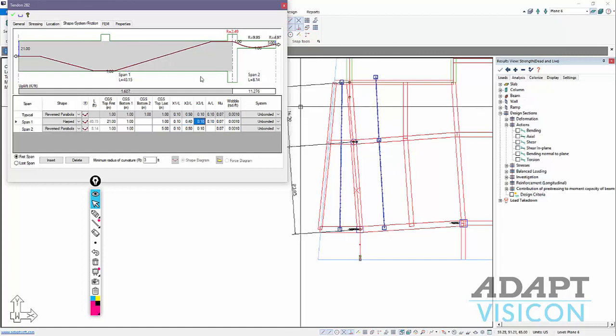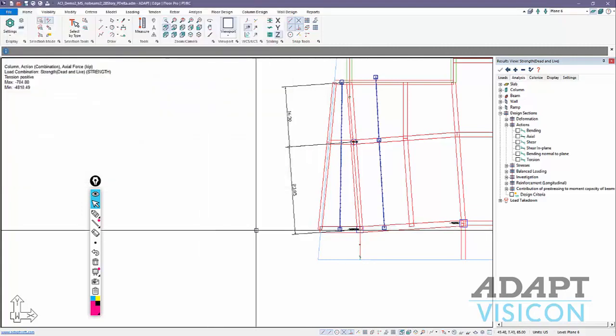And then the width of the straight portion of the harp is defined by A over L. We're going to say that's 0.05. And then we're going to say we want this to be located 3 inches off the bottom of that beam. We have an anchor point here. That anchor point may need to be raised to be at the CG of the effective centroid.